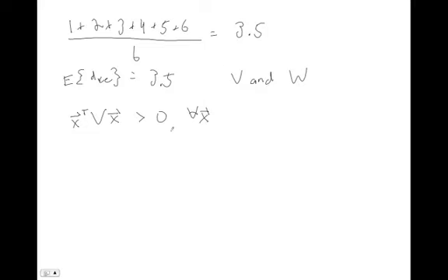So V and W are positive definite matrices, and in general they could actually be 0, but we are going to assume that W is strictly positive definite, meaning that there are no clean sensors at all. Every single sensor has some noise on it, so it's impossible for you to ever get any zeros in this matrix.